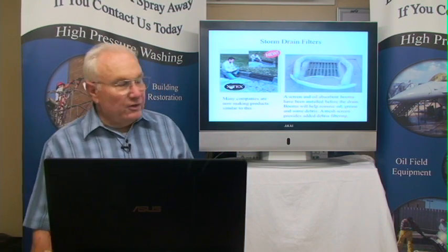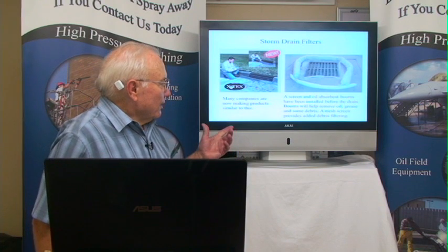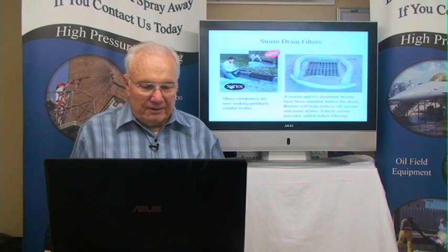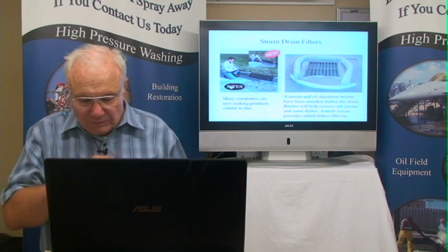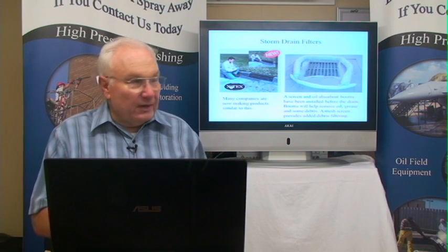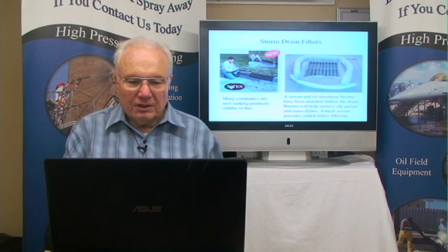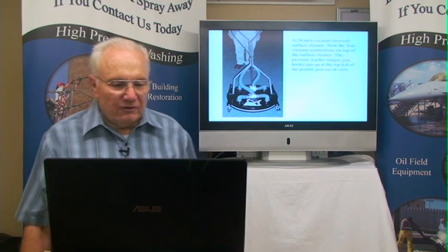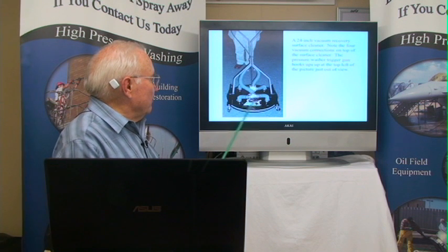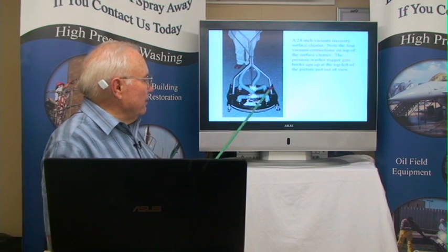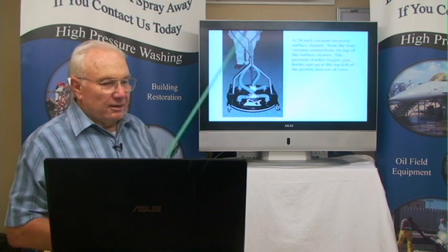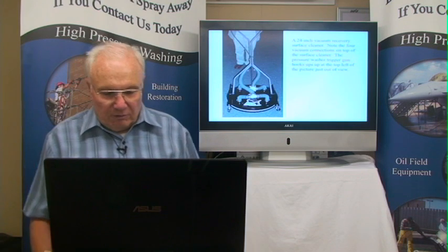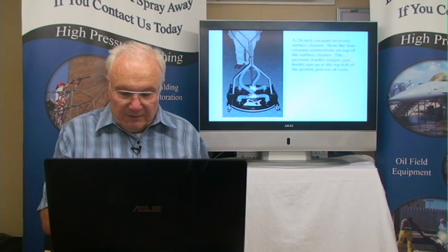So the methods of filtration want to be the most effective thing available, and if that's the most effective thing available, fine. You need to check locally. That will meet the requirements of the model ordinance and is legal in the city of Fort Worth. This is a vacuum recovery system. This is a surface cleaner that picks up the water as you put it down, and when operated correctly, they'll leave the surface damp and pick up all the wastewater. That way you don't have to put down all this water capture equipment. You got it right in front of you.